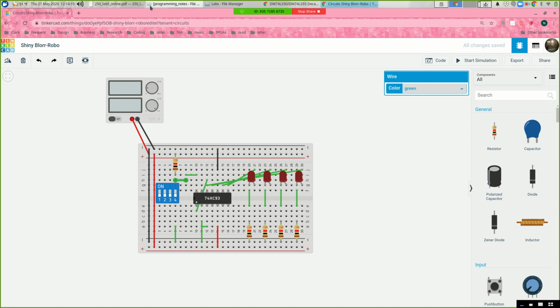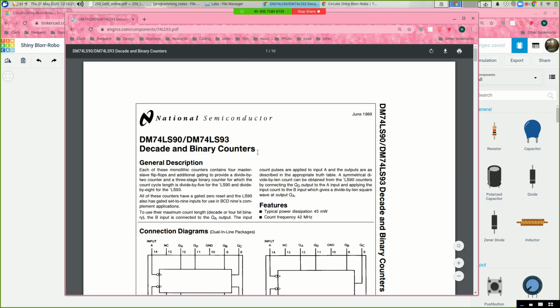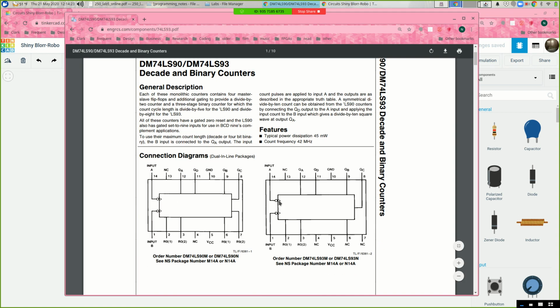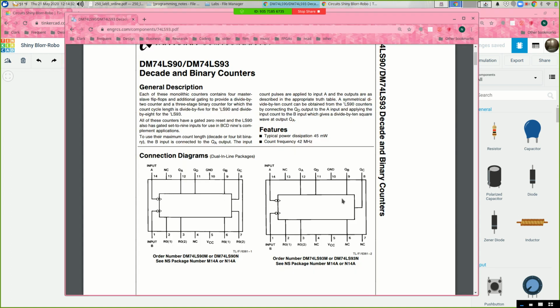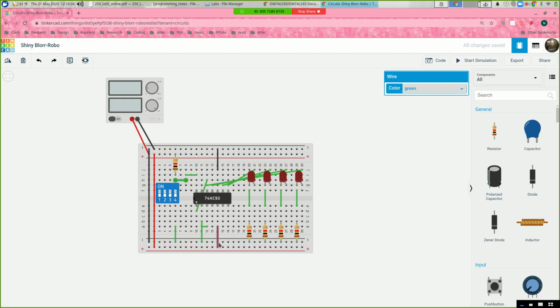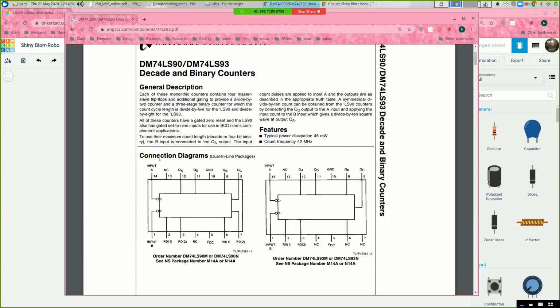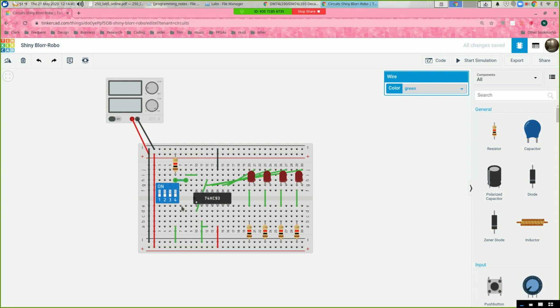Alright. So let's double check what we did. This is the clock input on 14. 13 has no connection. 10 should be ground. That's 10. 5 should be power. That's power. The switch isn't touching the other side. That is in fact a problem. Thank you. That would have been like the last thing I checked after an hour of checking wires.